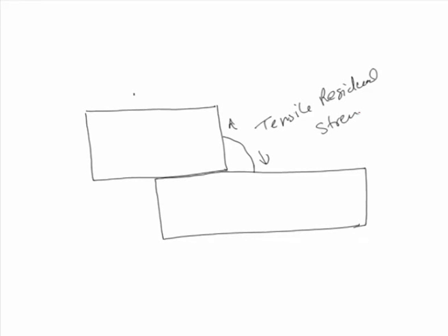This is an important aspect, and we can understand it from this diagram here. We can see that if the plates to be welded are very thick, and we put in a fillet weld of very small size, then due to the development of heavy tensile residual stresses acting on the fillet weld, it will tend to crack.